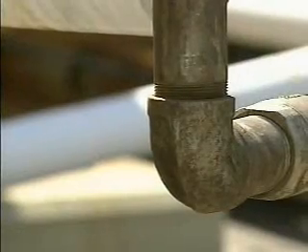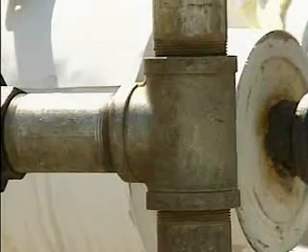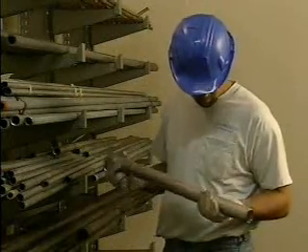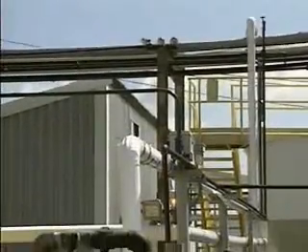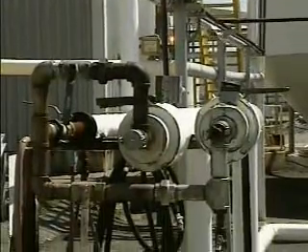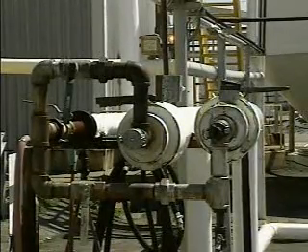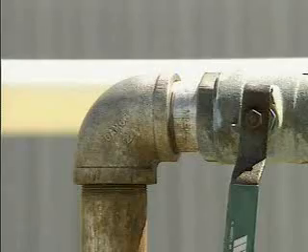Another material that's commonly used to make pipe is stainless steel, which is a steel alloy containing 12% chromium by weight. The relatively large amount of chromium contained in stainless steel gives it corrosion resistance superior to carbon steel and other low alloy steels. Since stainless steel is stronger and stiffer than materials such as copper, it is well suited for use in high temperature and high pressure systems, such as hydraulic systems.